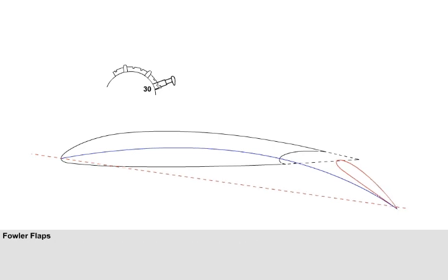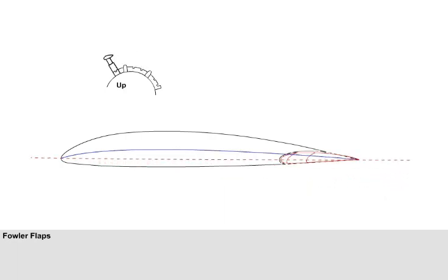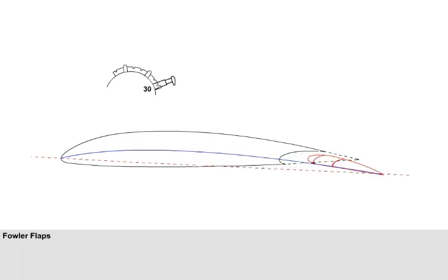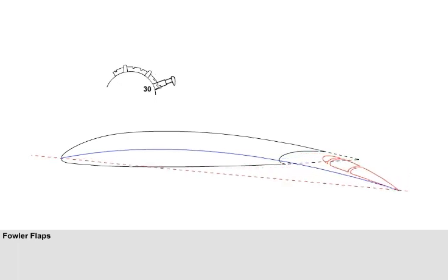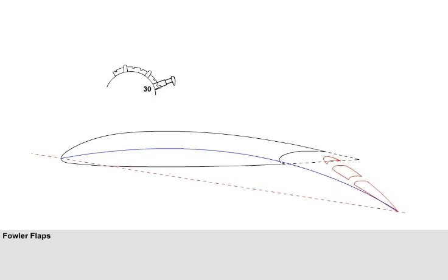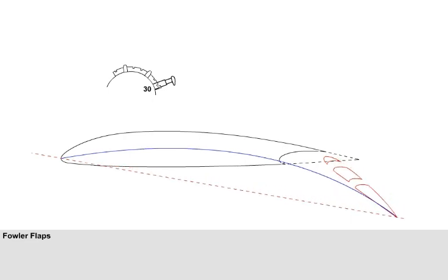We will now select flaps up. This is a non-practical selection and speed of operation. If you selected flaps all the way up like this when flying, the aircraft would sink like a stone. We are resetting the scene to consider slotted Fowler flaps. For maximum efficiency, Fowler flaps can have as many as 3 slots. This example shows triple slotted Fowler flaps as fitted to large jet transport aircraft, such as the Boeing 747. Again, this animation is not practical. We are merely showing the type of flap.